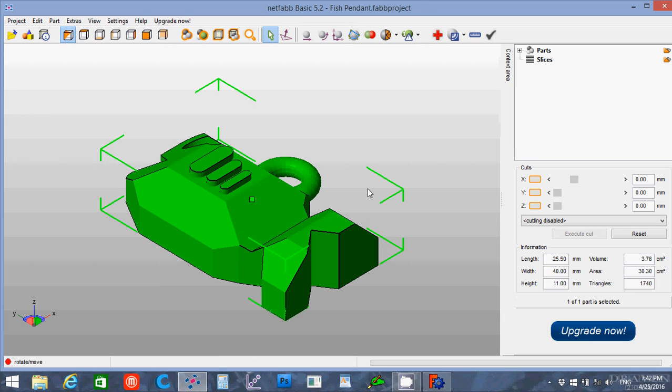And that's it, this is now ready to be 3D printed. And if I was going to 3D print this on an FDM machine, I would use supports because I hollowed it out. But for an FDM, you don't have to make that back cut into the object. But if you wanted to 3D print it through Shapeways, you could use aluminum or stainless steel or any of their other metals, then you really want to try to cut down on the amount of material you're going to use when you actually 3D print it.